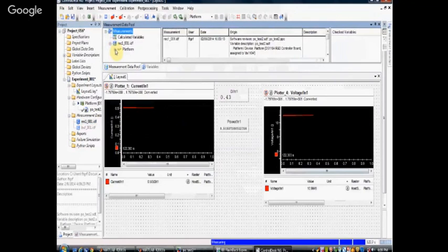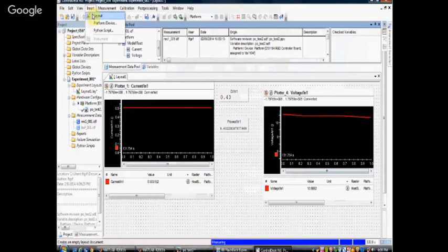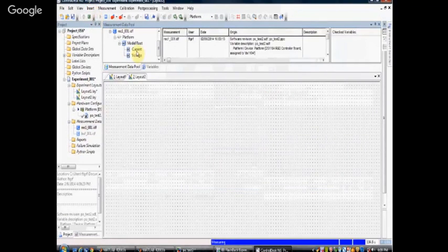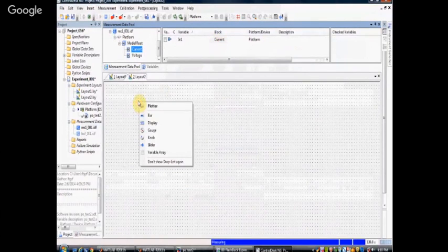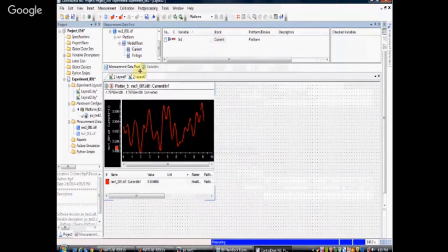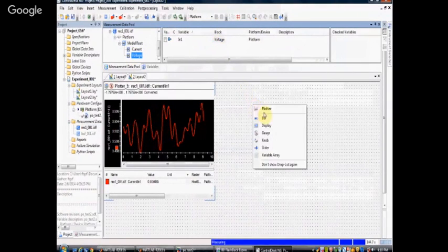The recorded values are here. You can just go and see all the parameters which you want to see. Model root, voltage and current are there. If you want to see what is recorded, you can go to Insert, have another layout, and drag these parameters, and these are the recorded values. This is at one particular instant, it is just showing me what it has recorded.